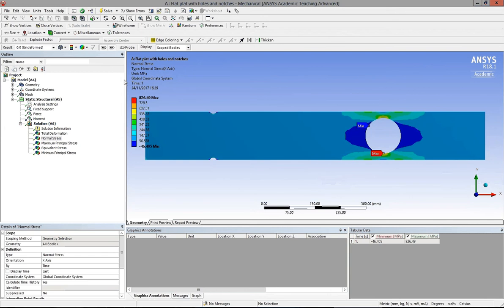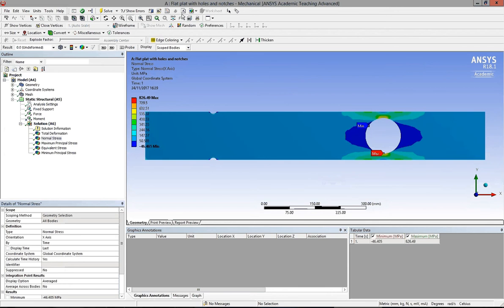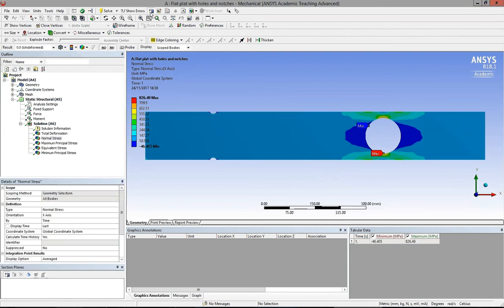There is another way which you can section. Now let me see, up here there is an icon called section plane. So if I click on that, new section plane, down here in the bottom left hand corner we have some icons to manage these, and we can basically take a cut down through, say there, and it does that.